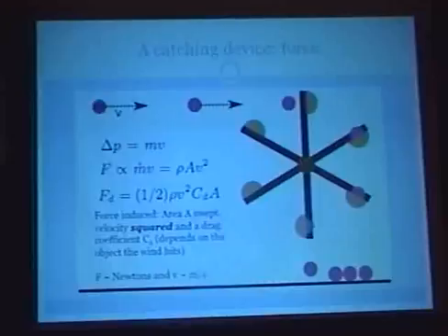That is, if you put a big square in the wind, it'll feel a lot of drag. But if you put some aerodynamic teardrop shape, say, it will feel much less drag. And the way that's encoded here is that you multiply it by this dimensionless drag coefficient. So for something like a square, this is close to 1, and for an aerodynamic shape, this might be 1/10 of that. So the force is proportional to the velocity squared and this dimensionless coefficient.